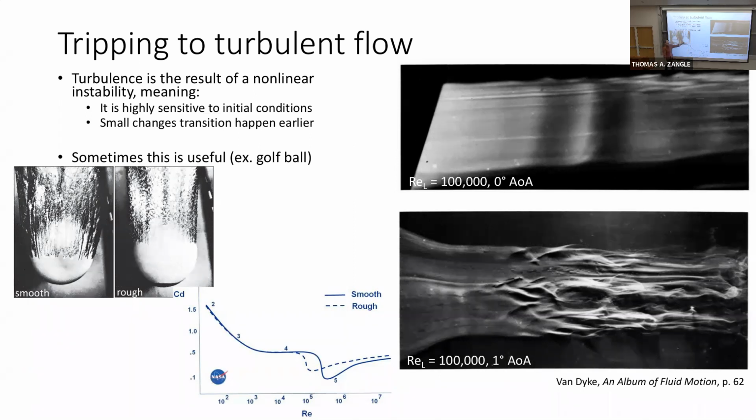From laminar to turbulent. And what we can see is that with a rough sphere, so if we just roughen up the sphere a little bit, make the surface of the sphere a little bit rougher, then we drop from this solid curve to this dashed curve, and there's a pretty substantial difference in drag coefficient if we do that. Okay, we're going to talk about why this occurs, but the main concept here is that small perturbations can give rise to an earlier onset of transition to turbulence.